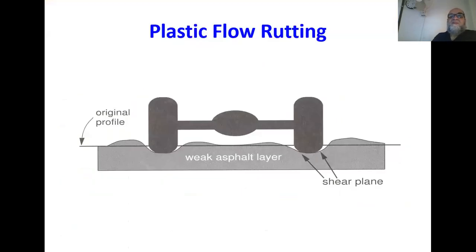Most of the problem in Pakistan is rutting. So let's try to understand at which depth the rutting has occurred. The rutting can occur within the asphaltic layer. It means the thickness of the asphaltic layer is not adequately designed. And you can see evidence of that if you have a straight profile, you will find some upheavals there. So this only happens where your asphalt layer fails.